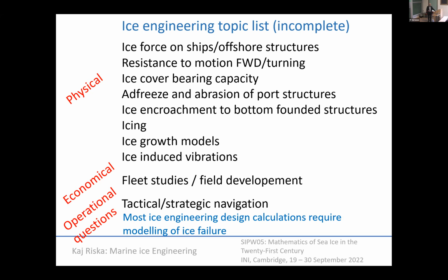It's not really a hazard. It's a hazard only for very small ships, like fishing vessels and all that, because of the stability problems. Icing is occurring on an area, and stability is a question of volume. That is why it is only for smaller ships. Bigger ships, it's a nuisance. You have to warm radar scanners and stairs and all that to avoid ice, but that is just a practical thing.